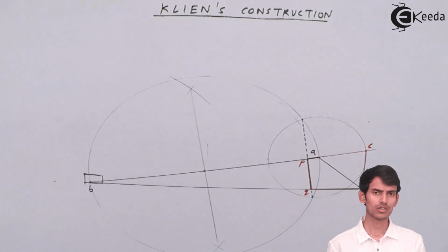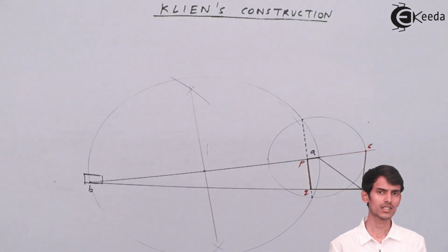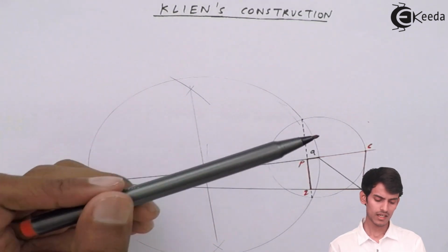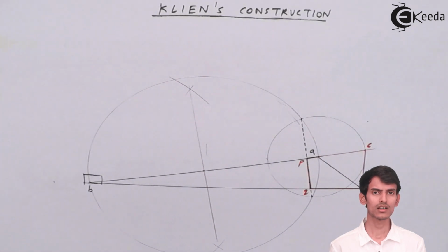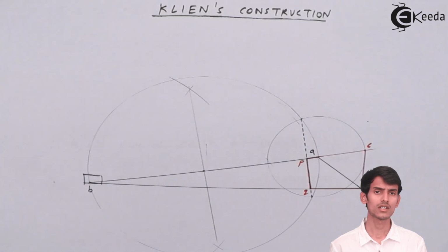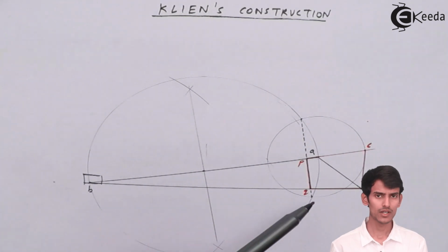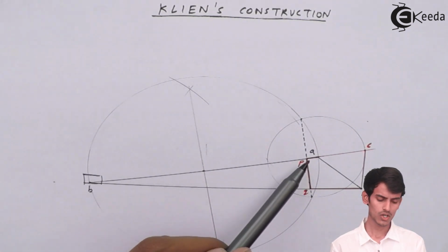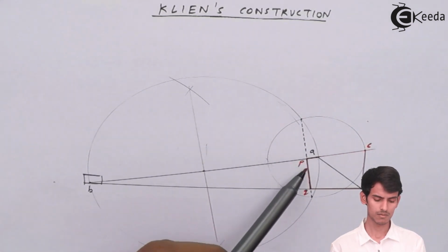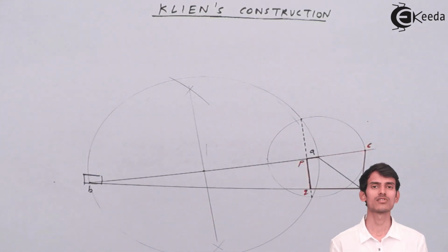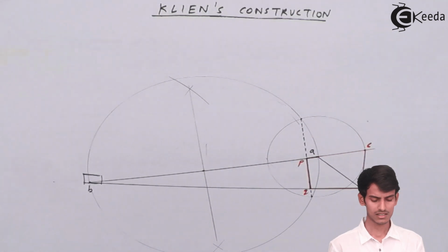The two circles will intersect each other at two different points. Join the two points by a dotted line, and that dotted line will intersect the connecting rod somewhere. Name that point P. That dotted line will also intersect the horizontal line somewhere. Name that point Q. The part of the dotted line between the connecting rod and the horizontal has to be made dark. That is the PQ part. So you get a quadrilateral OAPQ, that is the acceleration quadrilateral, and different lengths will tell you different things.